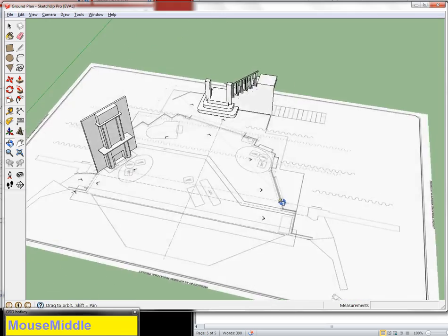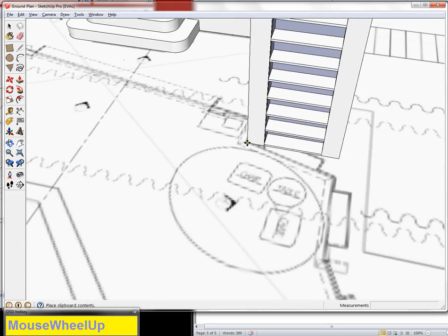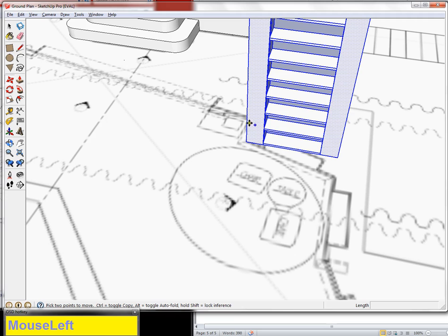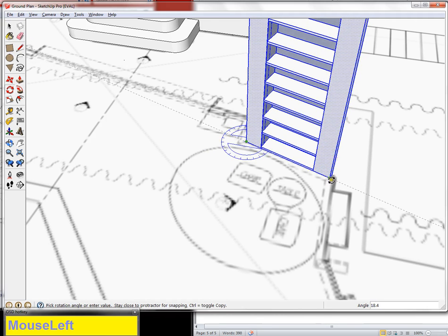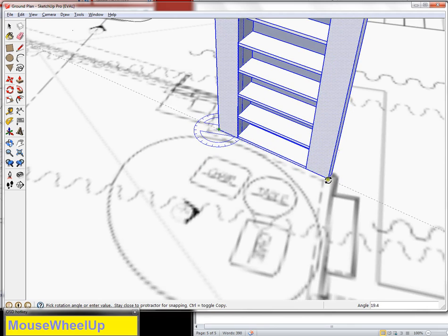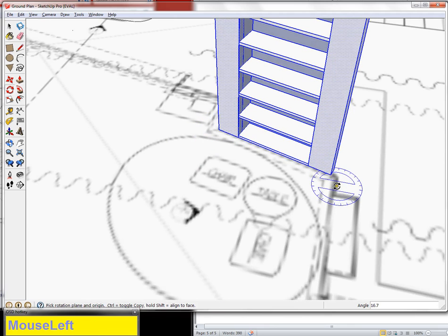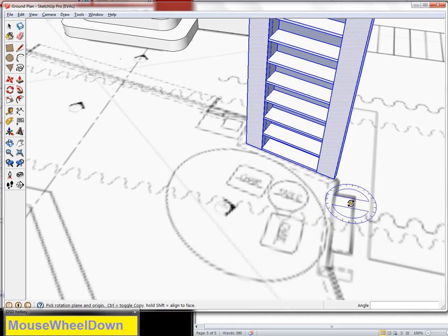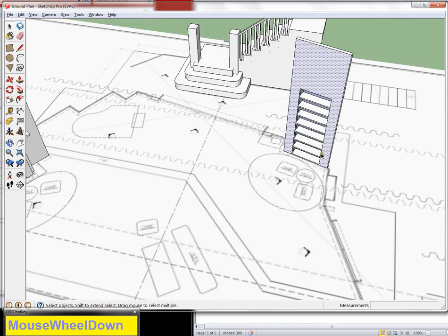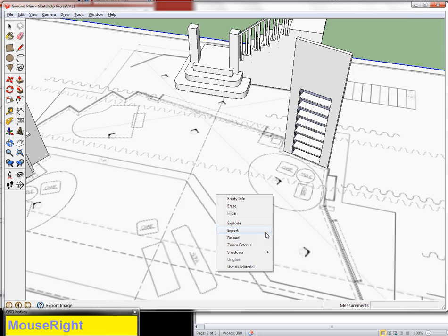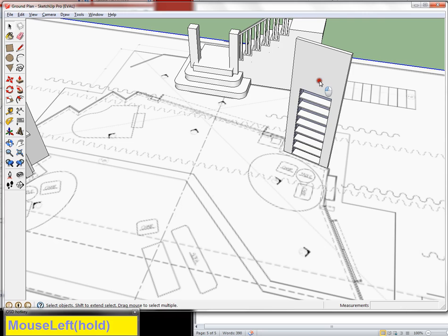paste. Now again, this one is a little bit difficult because these walls are not actually square. So unlike the staircase that just kind of plops in, this one you have to rotate like you did the fireplace. I'm going to click this one picture, and I can't make it a component because it's not an object.